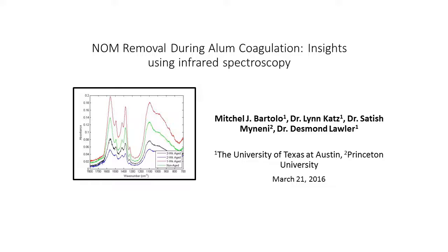Thankfully, biology does something for us there. It's another technology that is high. One small point, there's a lot with the Henry's coefficients, that the brominated ones are going to be removed less than the chlorinated ones. Of course, we regulate on the total. There's extreme sensitivity right now with the brominated ones. I think the experience so far is that they're removing pretty much all the THM species, even though the Henry's coefficients would suggest the chlorinated over the brominated.